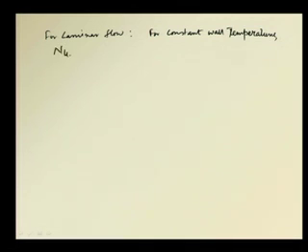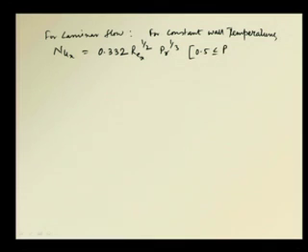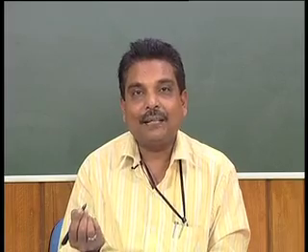Okay. Now, if we see for laminar flow and, say, constant wall temperature, we have Nusselt x. We can understand that Nusselt number is becoming a local Nusselt number. We will discuss this. Nusselt x is equal to 0.332. This is a very well known relationship of Reynolds to the power half into Prandtl to the power 1/3, where 0.5 is less than or equal to Prandtl, which is less than or equal to 50, and the Reynolds number is less than 5 into 10 to the power 5, that is the laminar flow region.